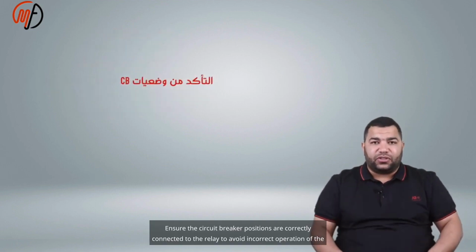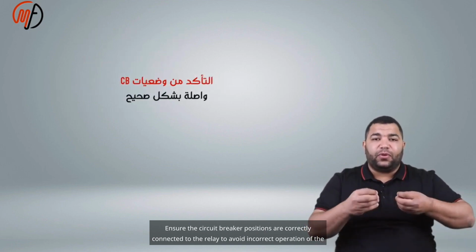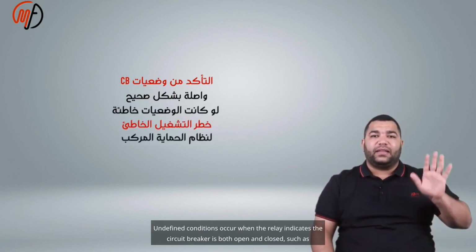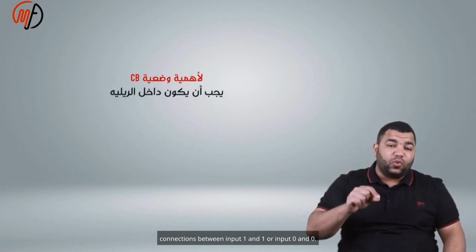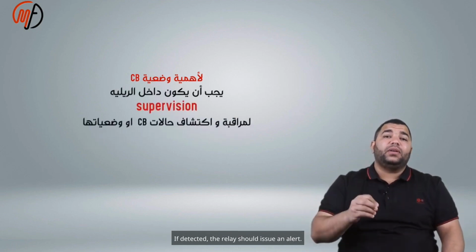Ensure the circuit breaker positions are correctly connected to the relay to avoid incorrect operation of the protection system. Supervision within the relay should monitor and detect circuit breaker states to identify undefined conditions. Undefined conditions occur when the relay indicates the circuit breaker is both open and closed, such as connections between input 1 and 1 or input 0 and 0. If detected, the relay should issue an alert.